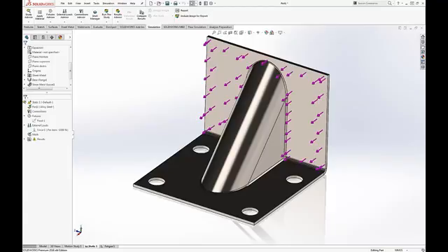can lead to, let's say, an instability of the geometry, okay, not of the material. But I would like to understand which is the value of the instability. And this is linked also to resonance, because basically we are trying to understand which is the first resonant frequency and how much load is needed to put it at zero. Because if I use a compressive force, I will decrease the first resonance frequency. So it's connected. Okay, let's do it.